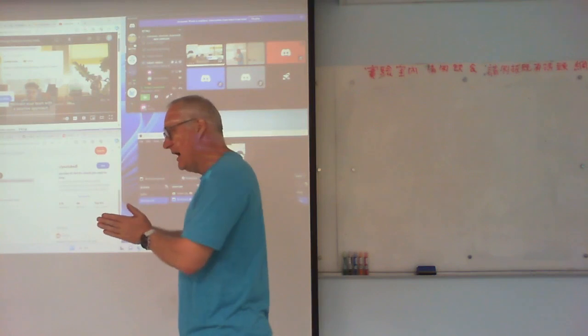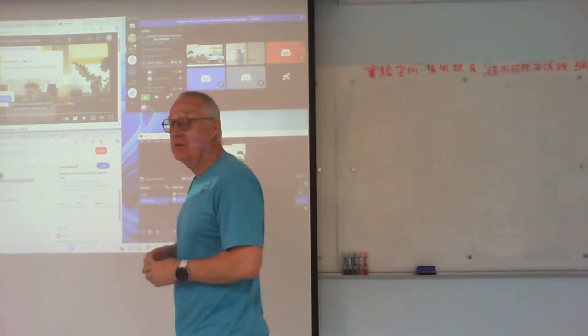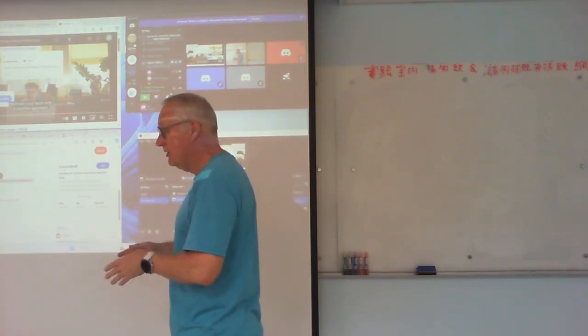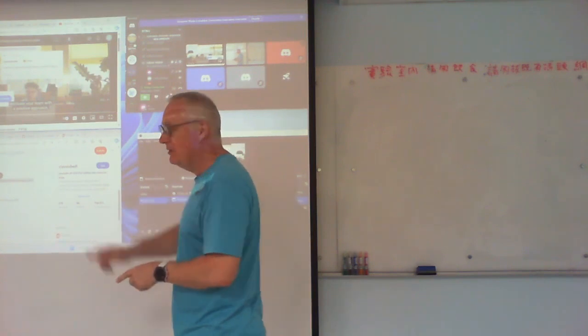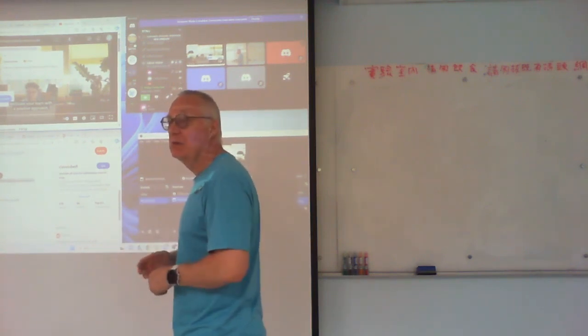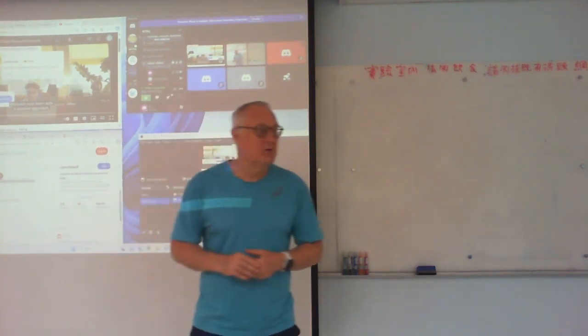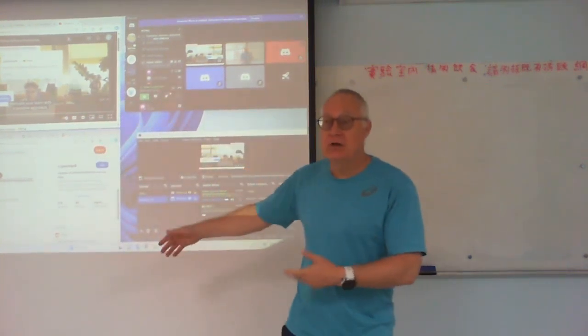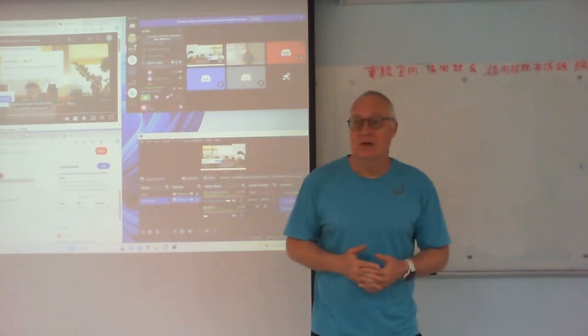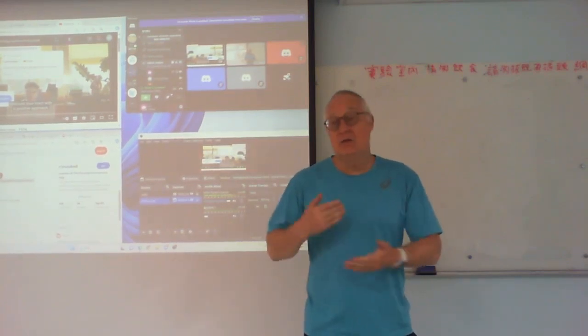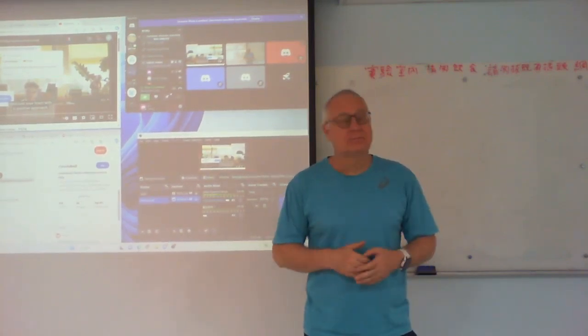Depending on whether you have your orientation information or not. If you don't have it, you actually need 3 points. Otherwise, 2 points will be sufficient. Then you can use that to actually localize your robot within the field of view that you had before. And then you do that continuously.